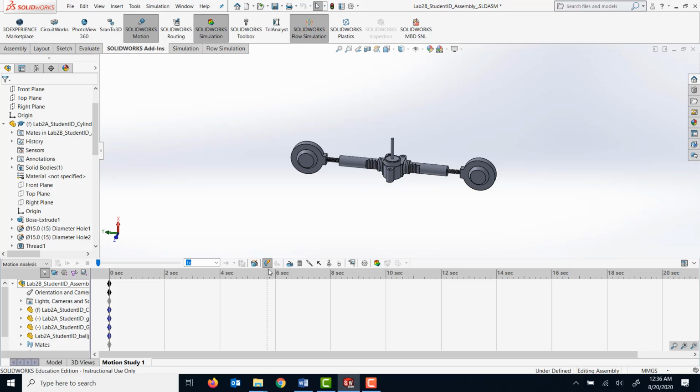With the kinematic analysis, you're basically solving for equations of motion where no dynamic forces are involved, or there are no torques, those parameters are not calculated. With the basic kinematic analysis, you're just basically solving for displacement, velocity, and acceleration, and so on and so forth.